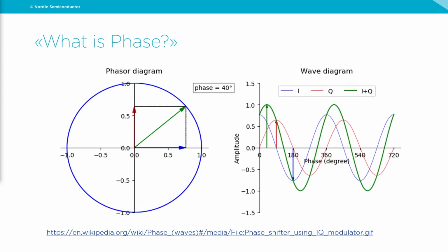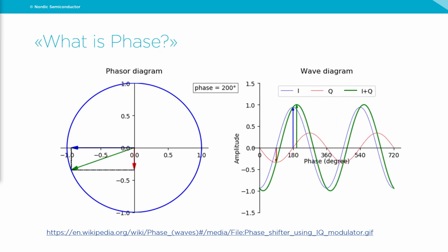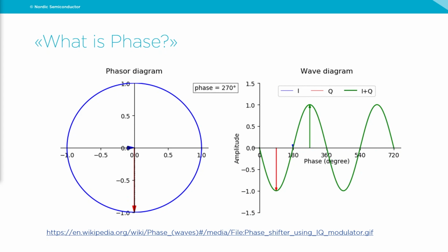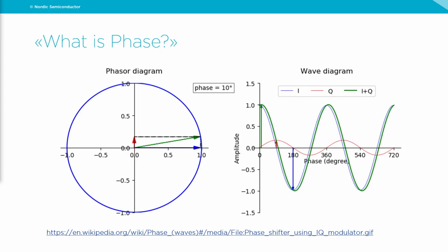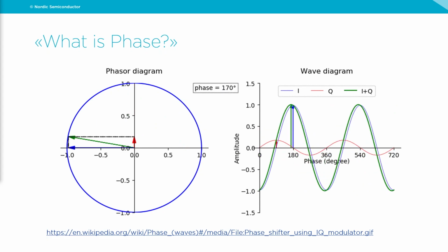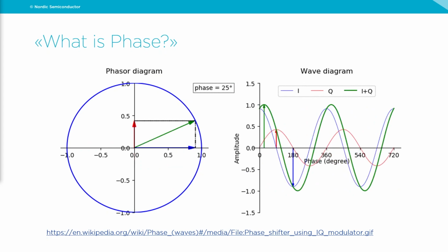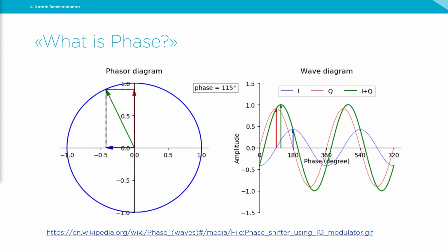So normally in the radio, you do demodulation with 2 carriers that are 90 degrees phase shifted, and then you get the I and the Q data. When you have both of them, it is much easier and much safer to convert from those I and Q data, reconstruct the signal and get the phase data out directly.